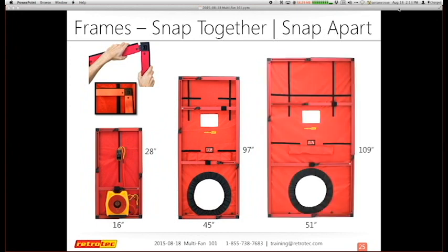So recently Retrotech released the Passive House. They call it the Passive House frame, which is basically the window frame for the duct tester. And depending on how tight your home is or how small your unit is, that may do fine for doing a blower door test. It also can turn sideways, so it doesn't have to be vertical. The standard frame is in the middle. It does have some really cool pockets in the middle if you've not seen that.